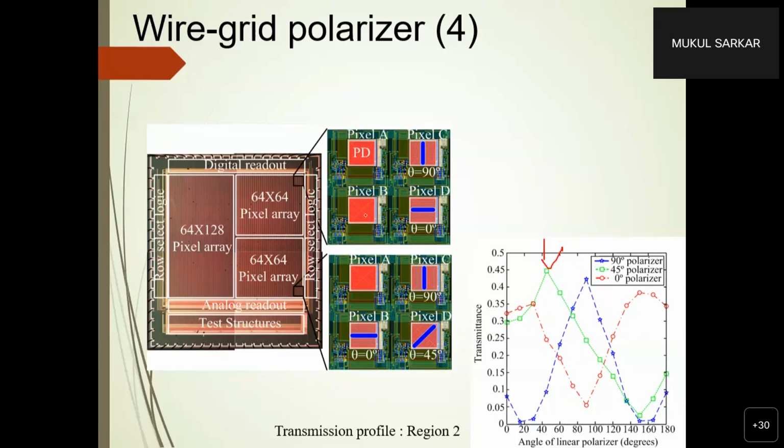However, there are different aspects to power consumption, right? It's the power consumption of the pixel, the power consumption of the column, the power consumption of the frame, and at what speed you're operating, 30 frames per second or 100 frames per second. All those define the power. So if you want to go lower in power, spatial resolution is one thing, but you also have to see the temporal resolution as well as the noise and the optimal readout of the column, because all column readouts are designed at a minimum readout speed, minimum power. Those optimizations also need to be done if you want to reduce the power.